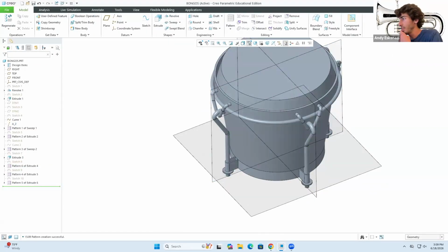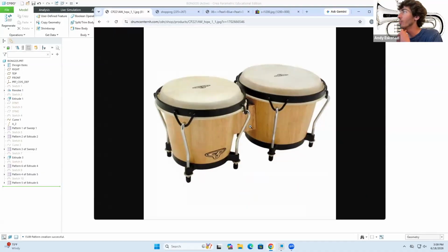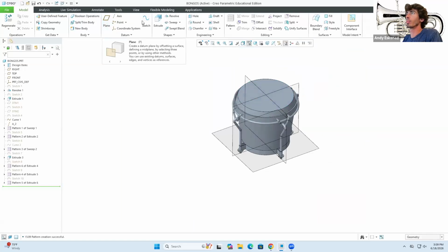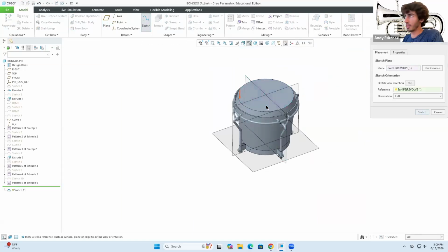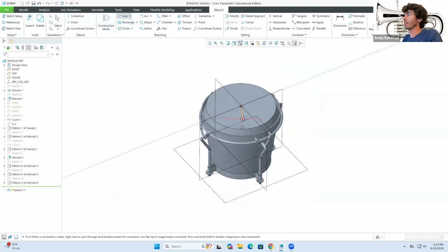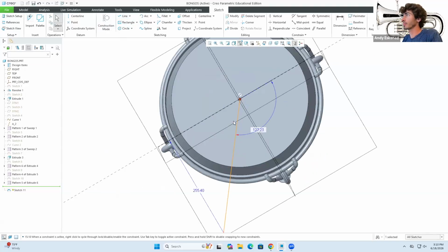So now that we have this thing, we just have to do that little wooden piece that goes in there. So the approach to do that is to go here to a sketch over in this face. And now I just need to draw a rectangular line, a line that really will go like this. Let me just draw at a 45-degree angle.